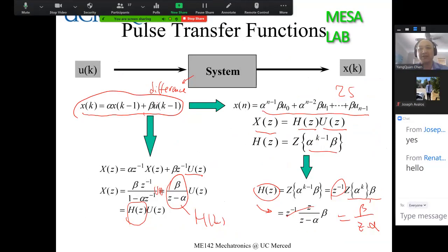From this difference equation, you have an input signal, any type of non-constant signal. It's possible to do it in a very simple way like this. You simply say my output X(z) will be (zI - A)^-1 times... X(z) = (zI - A)^-1 B U(z). So then this is actually the H(z). This is called the Z transfer function.